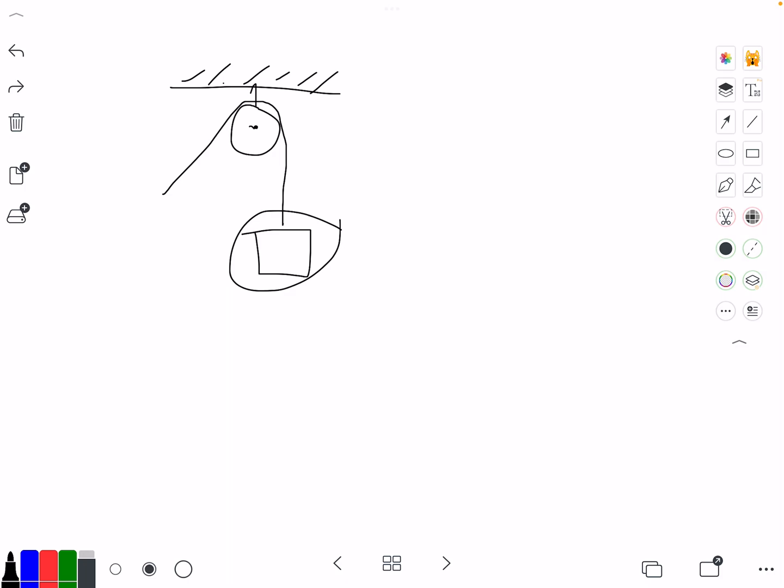So in this case, with the fixed pulley system, if we have our force of effort here, that force is going to be translated through the rope and be pulling up on the load. So let's call that FL. Now in this case, that force is constant through the rope, and it's a 1-to-1 ratio. So we're going to say that the force of the load is equal to the force of the effort. So any kind of force, if you apply a Newton or 10 Newtons or whatever it is, that force will be directly mapped to the load as a lifting force.